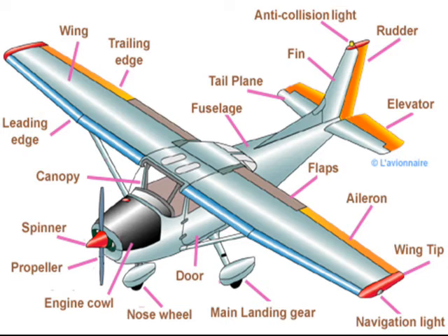The second point is, it must be large enough to give sufficient tankage space, but at the same time it should be as small as possible to reduce the wind resistance. It should have enough depth for strength, but it should not be very deep, because in that case the side area may become very large, which is undesirable for safety and efficiency. These are some of the required characteristics of the fuselage.